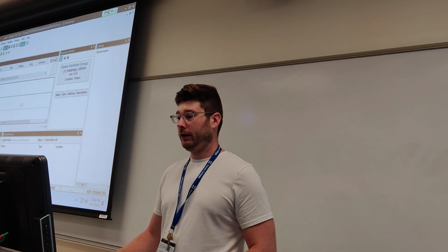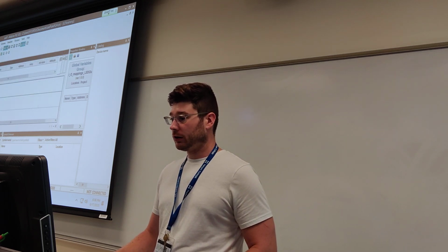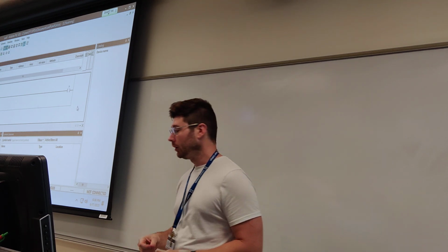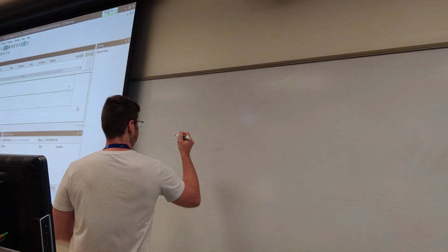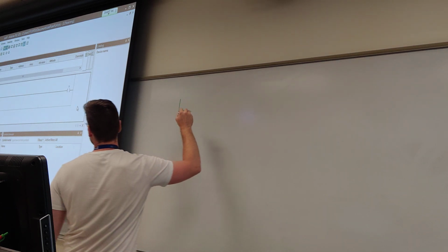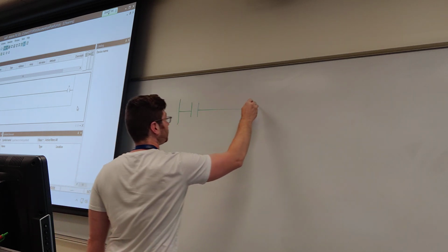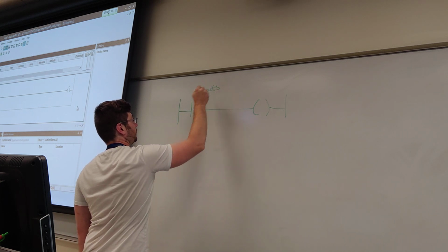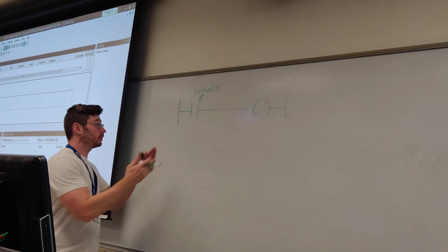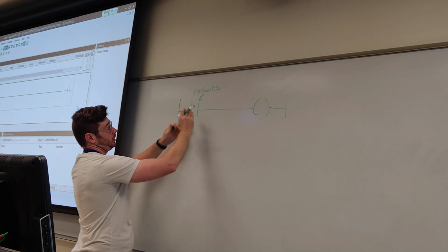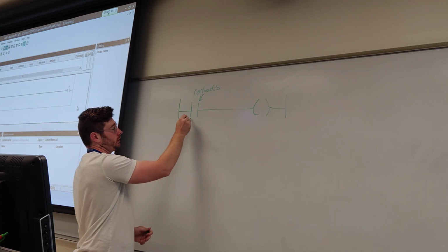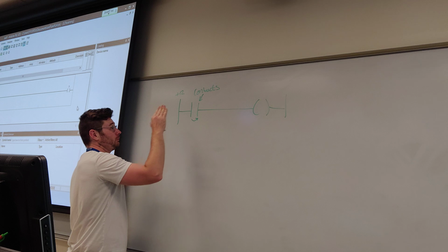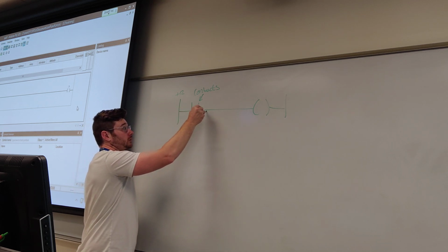Going back to our ladder diagram, this is our logic. Literally the program that says when this thing happens, this other thing should happen. The way that we should cognitively think about this, the cheat sheet in our heads, is that these are called contacts right here. You can imagine they're two pieces of metal that could come together, or if you put your fingers here, you would bridge the electricity to jump across. Imagine this is like a powered rail. If you were to press this button, the power could continue on down the rail.